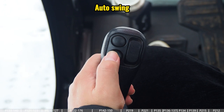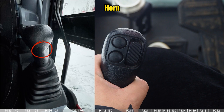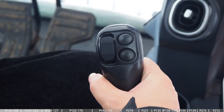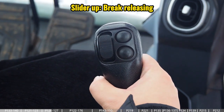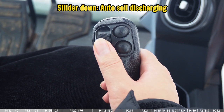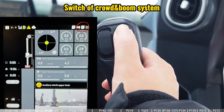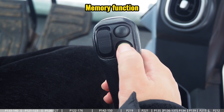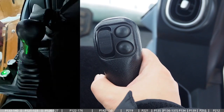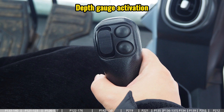And this button is for the auto swing function, and at the back of the joystick we have another button for the horn. For the right joystick, pushing the slider up is for the brake releasing function, and pushing the slider down is for the auto soil discharging function. And this button is a switch between the crowd system and the boom. And this button is the handle memory function. And also in some kinds of machines, we have another button at the back of the joystick, which is for the depth gauge activate.